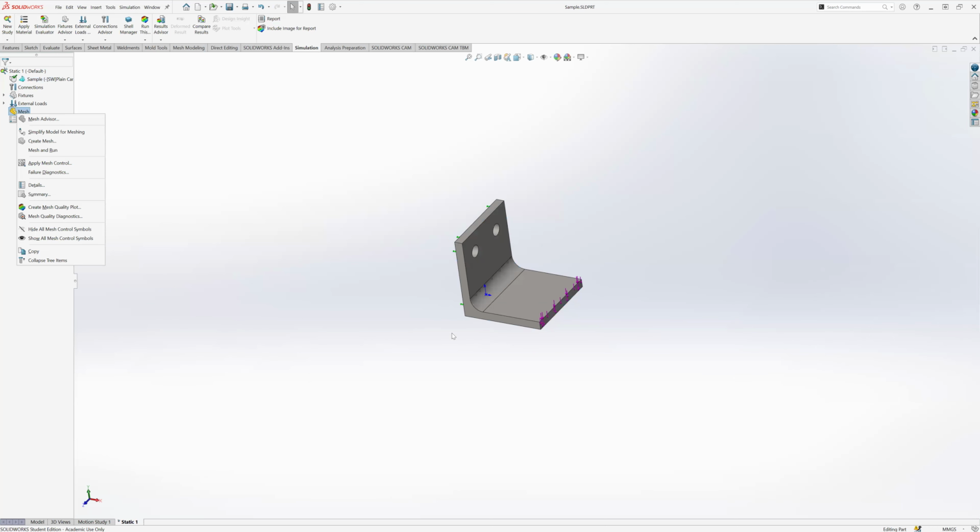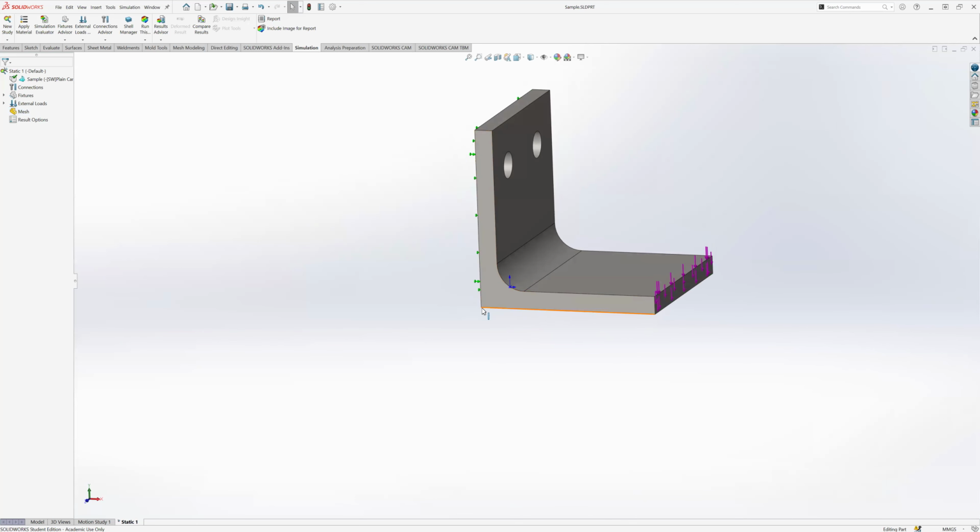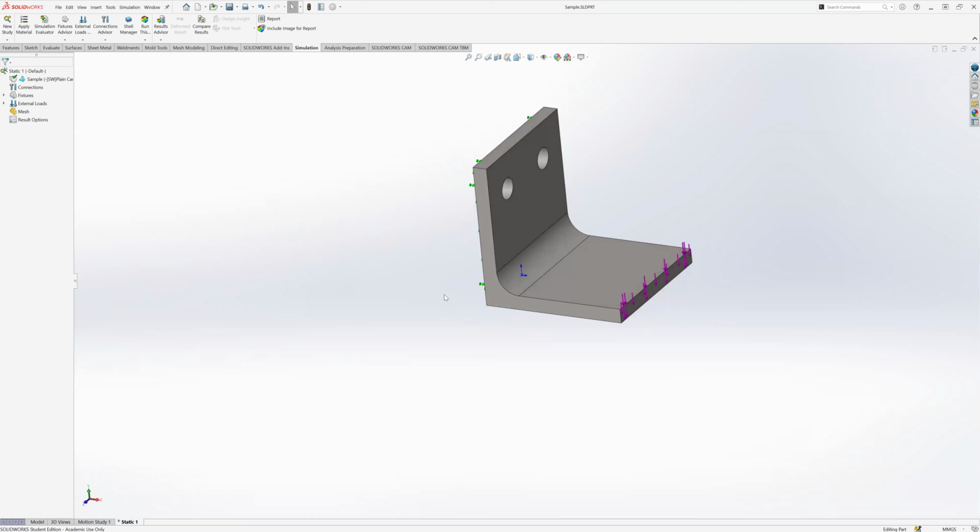This is going to be a solid mesh, based on the geometry we have. For a shell mesh, it needs to have a constant thickness. It's going to be hard to treat this as a shell because we have a fillet here. If I had a corresponding fillet on the other side so that you had a constant thickness, then you could treat it as a shell. But it gets more challenging when you don't have a constant thickness. Okay, so getting into the mesh, the first thing you'll do is go to create mesh.